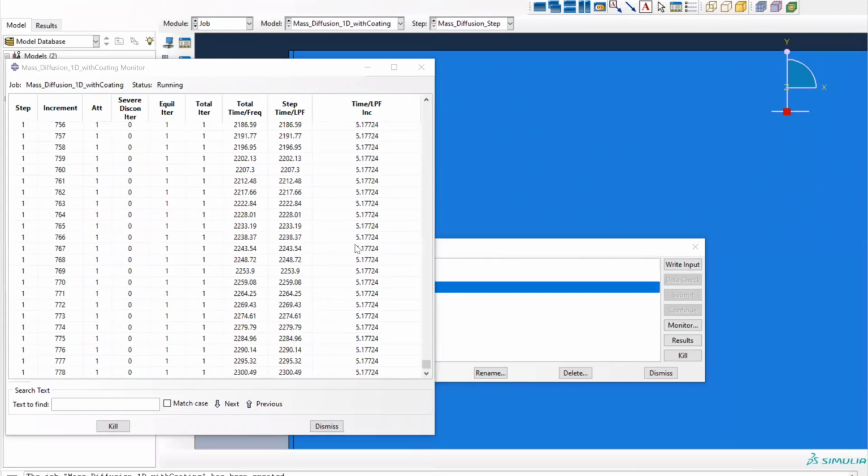So you can see that this process is taking a while. And so during the analysis, possibly it's wise not to have a very fine step, I mean increment size. Otherwise, your analysis won't be done, and you'll run into a lot of trouble. So yeah, it's good to test with this increment size.